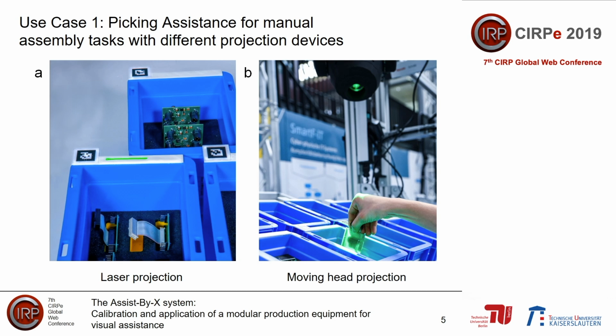The camera is a closed system which is able to communicate via MQTT using the AR markers. The locations of all the carriers on the workbench are detected by the camera and recorded with the corresponding marker's ID. Depending on the process step, the MES sends the ID of the component to be assembled to the camera system.